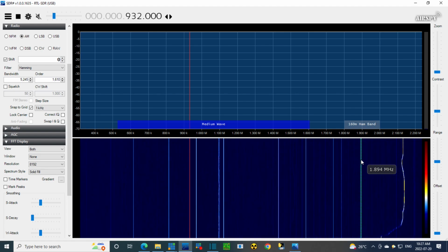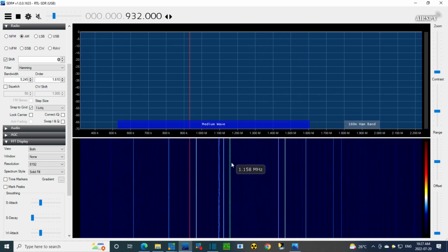So what I'm going to do now is tune the radio to a specific frequency on the dial. I'm going to pick 1 million because it's really easy. So that's tuned to 1 million. The local oscillator should be 1455. So where'd it go?